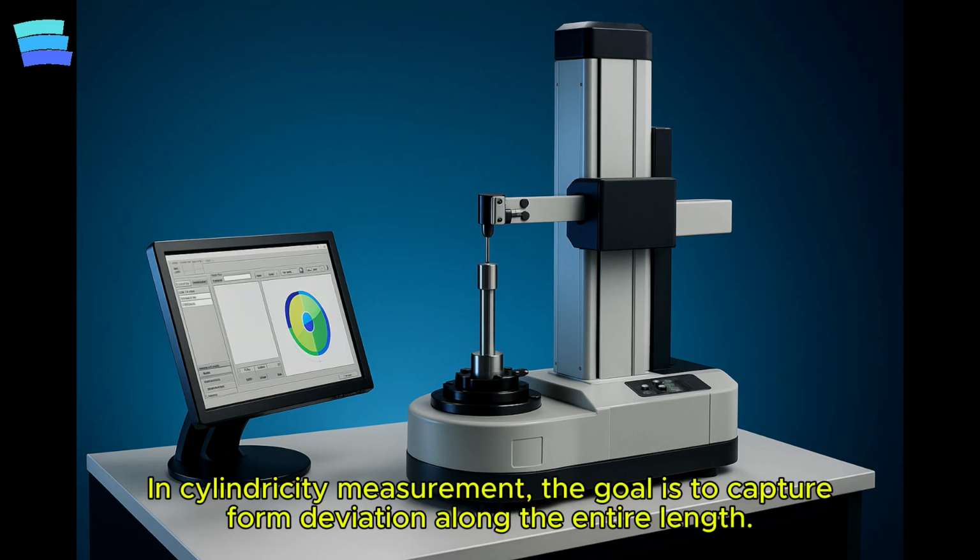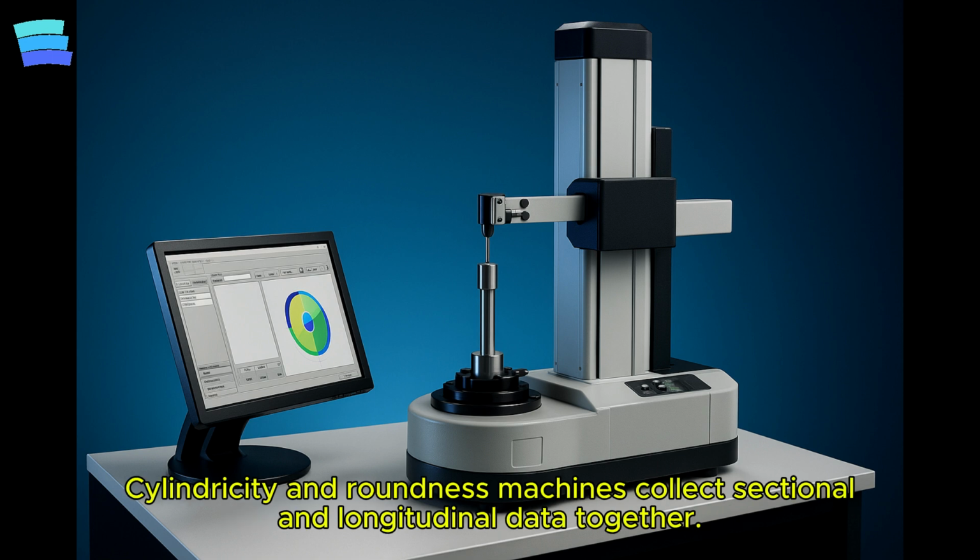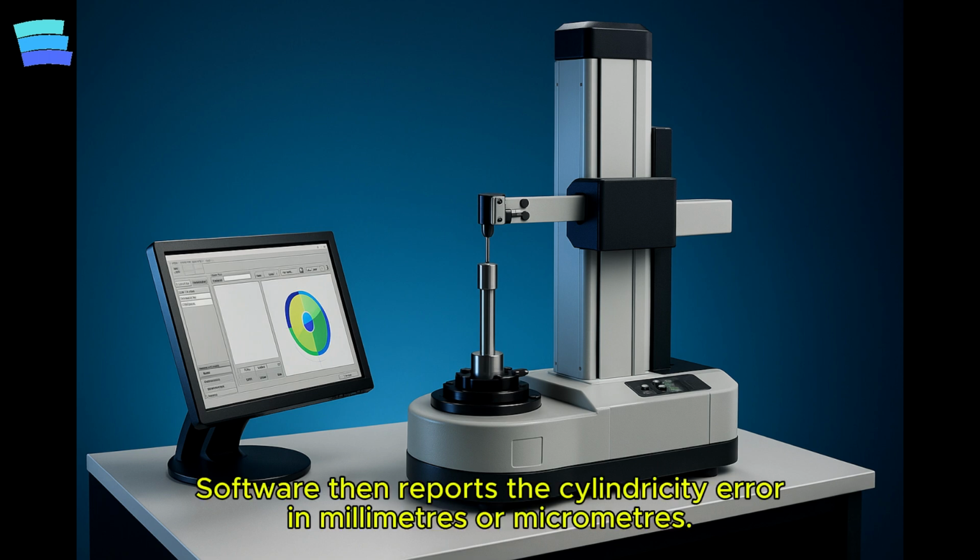In cylindricity measurement, the goal is to capture the form deviation along the entire length of the surface. The main methods used are cylindricity/roundness measuring machines. These special instruments collect both sectional data and data along the length, and report the cylindricity error in millimeters or micrometers through dedicated software.